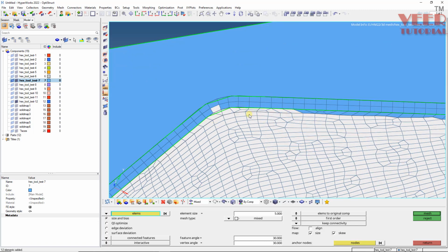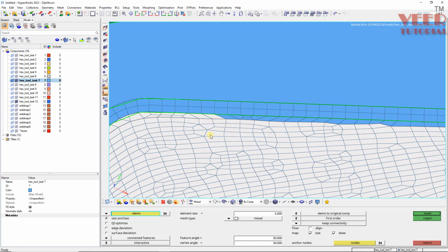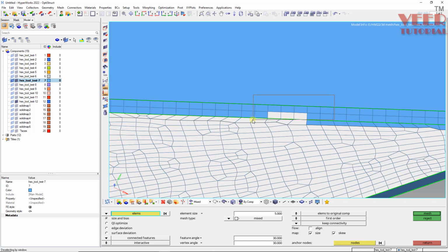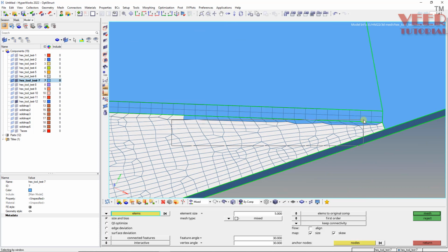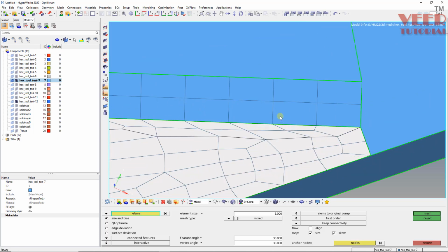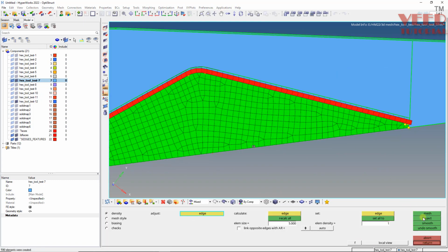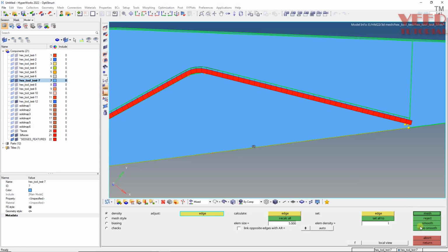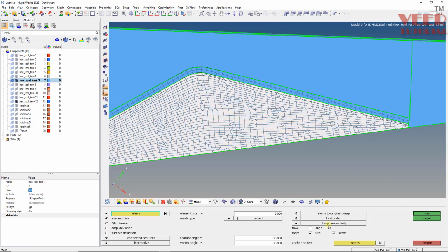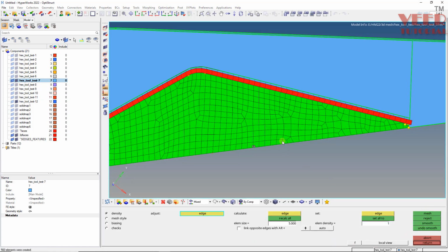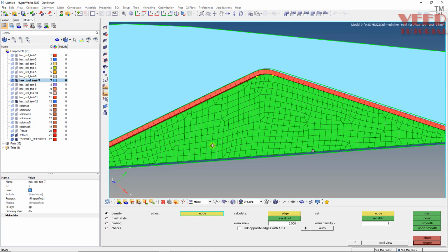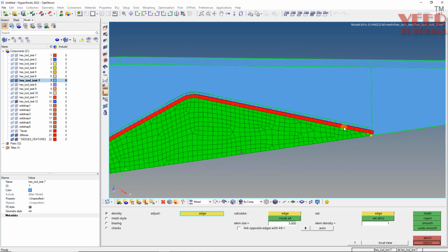Once again here select, and also select this, deselect this, and select this. Okay, now these are selected. Now I can do remesh, but here you can see try element, reject this, and return. Here it should be quad only, none, remesh. So now you can see we have a much better mesh flow this time.